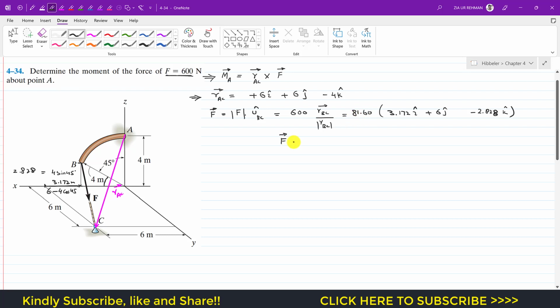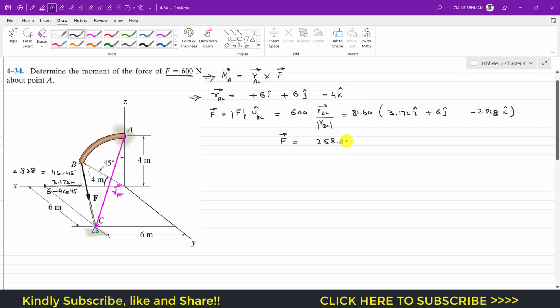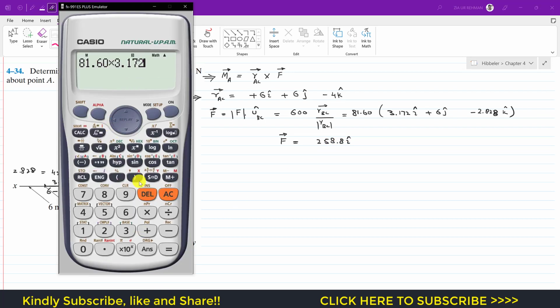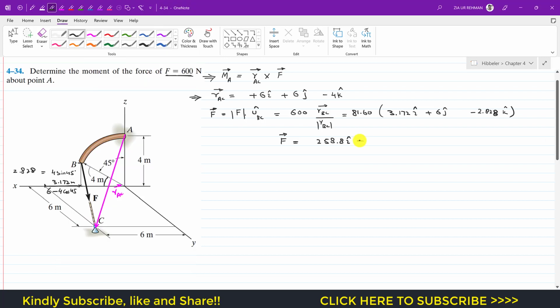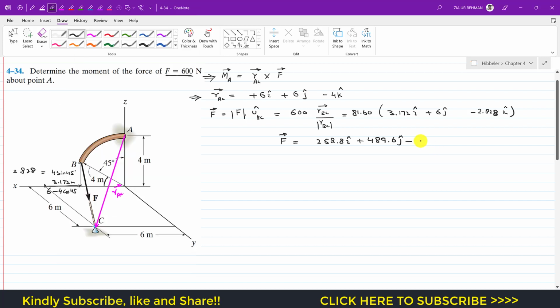Now for that force vector, we need to multiply this 81.60 with the magnitude of each component, that is 3.172, which gives 258.84 i, and then 81.60 multiplied by 6 gives 489.6 j, and then minus 2.828, and this gives us 230.76, this is minus k. So this is the moment arm from A to C, and this is the F Cartesian vector.